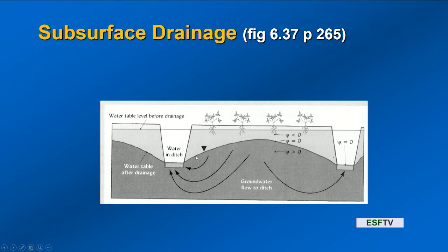And you space them, so you'll note that the greatest reduction in water table, or increase in aerated zone, occurs at the bottom of the ditch. As you get away from that ditch, the water flows to that point, and so it ends up getting these so-called hills, or higher points. So in order to control this water table, if we're managing a root zone, the spacing of the ditches is very important. The spacing of ditches depends on texture, and we'll talk a little more about this in organic soils. It depends on the rates of saturated flow, and this will have some pretty interesting impacts.